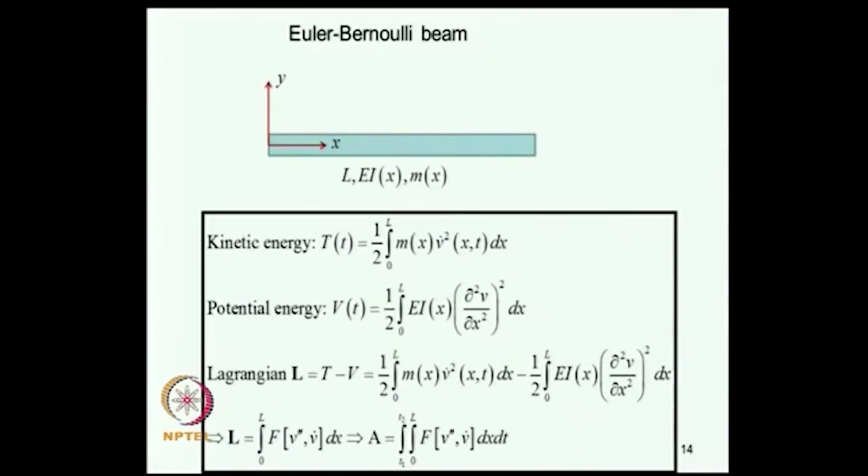Now, this logic can be extended to other structural elements like the Euler-Bernoulli beam, plates, plane stress elements and so on and so forth. For the purpose of illustration, I will consider one example, the case of an Euler-Bernoulli beam. This beam has span L, flexural rigidity EI of x and mass per unit length m of x. The kinetic energy is given by